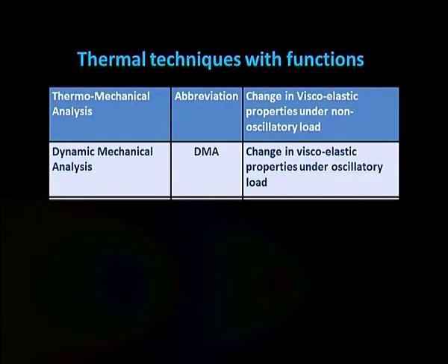Then we have dynamic mechanical analysis, abbreviated as DMA, in which the change in viscoelastic properties under oscillatory load is measured.